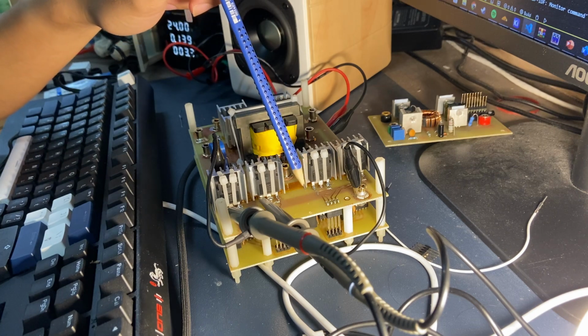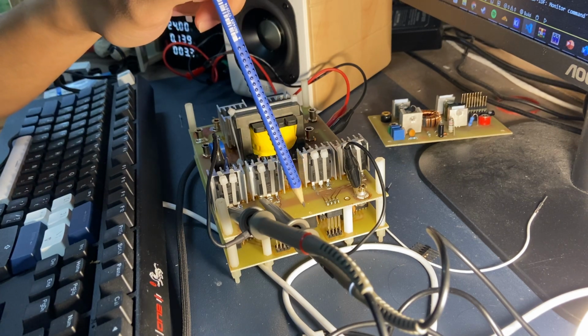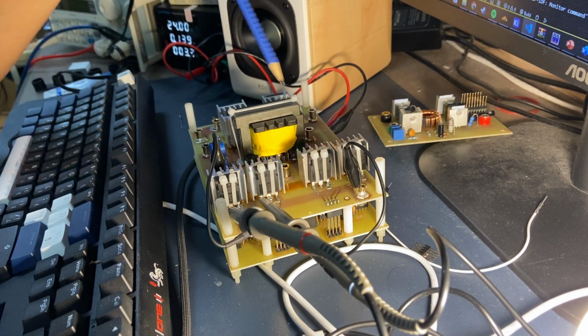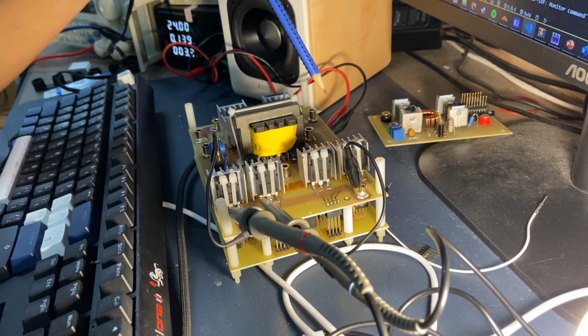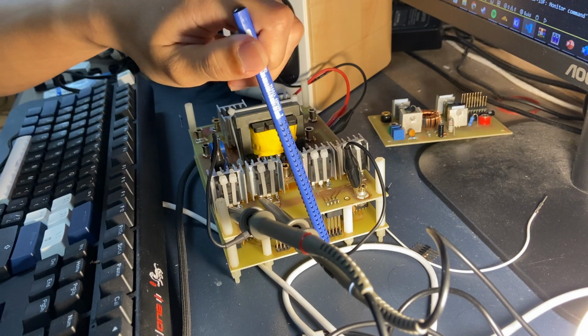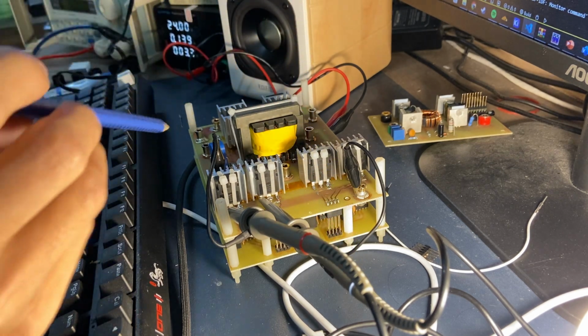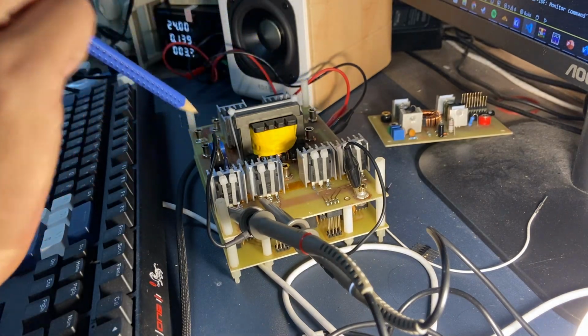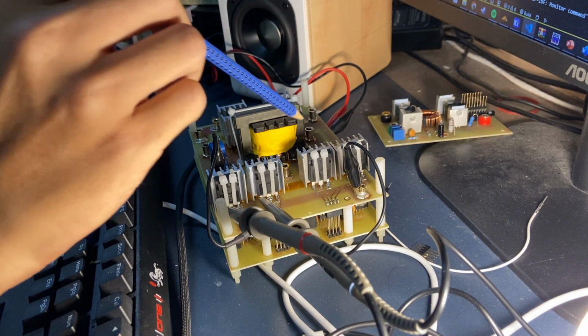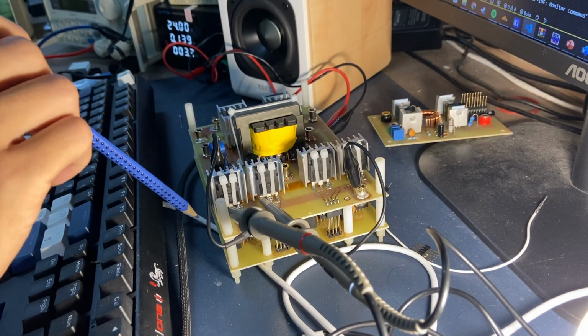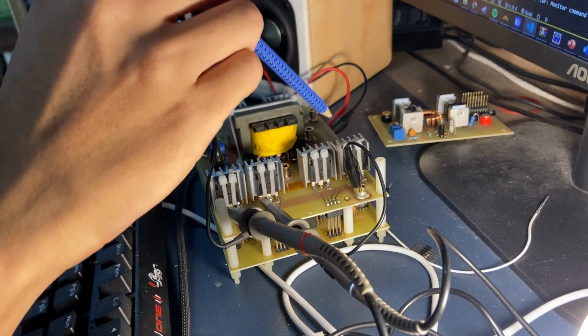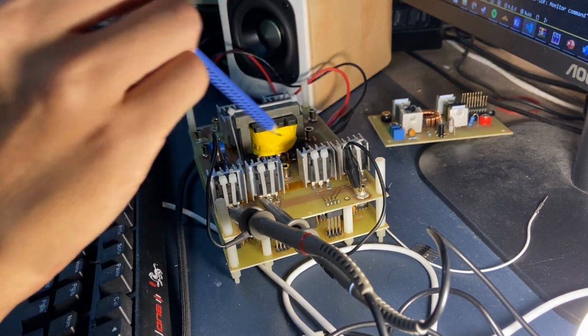So this board actually consists of two boards. On the top it's for the high voltage signal, the large signal, and then the bottom is for the small signal for the control. So for each MOSFET in here, the control signal is isolated by an isolated DC-DC converter for the supply, and then for the driver.